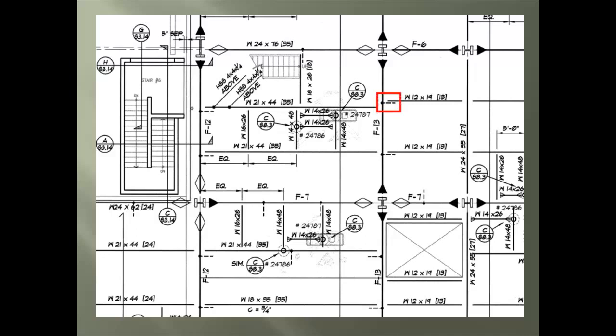This symbol is for the diagonal bracing tying the beam to the girder, and if you notice the dash line, it represents that it's under something solid, like the deck slab in this situation. Here, taking the same rule and reversing it, now when it's solid, as in a line, or in this case a box, it represents that it's coming up at you on top of that solid item, and here again it's the deck slab.